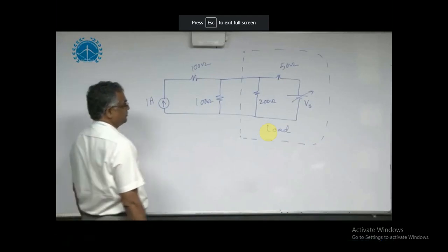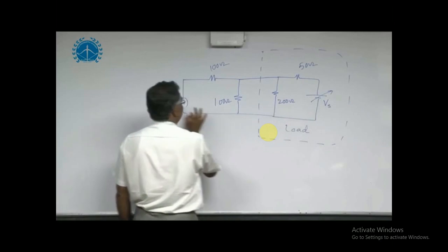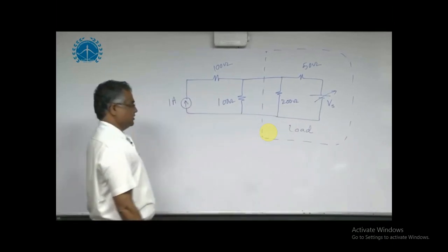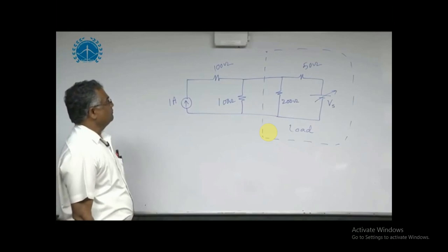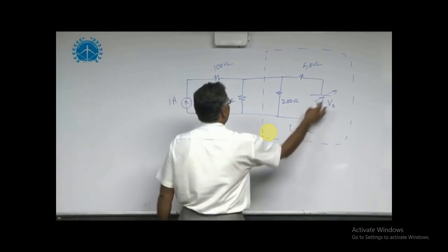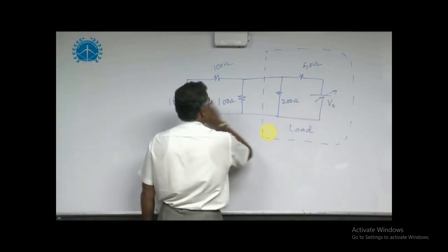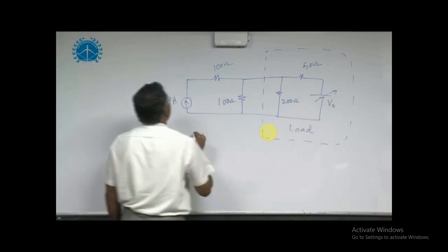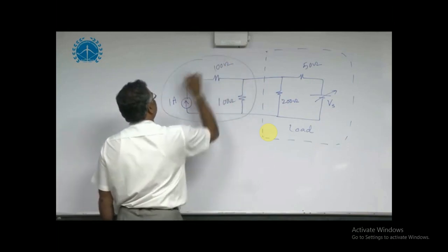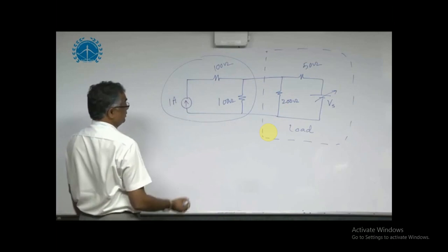Yeah, in this problem, for what value of Vs is maximum power transferred to the load? This problem comes under the maximum power transfer theorem. It is a special case because the load contains a voltage source. But if you observe carefully, the source is not in Thevenin equivalent form. So first replace this with the Thevenin equivalent.